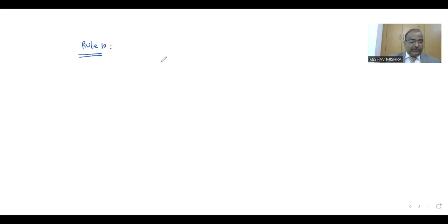If it is possible to eliminate the summing point, then the problem will be reduced step by step. So how can we remove the summing point? This is the elimination of summing point.